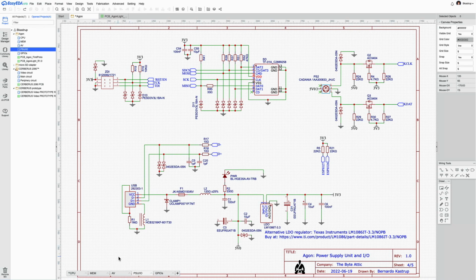Now, normally you would just connect the ground signal, which is this signal 4 here, straight to ground of the board. And you would also ground the can of the connector, the metal jacket of the connector, also to ground. This is what I think most people would do. The reason I added a large resistor and a little inductor is the following.